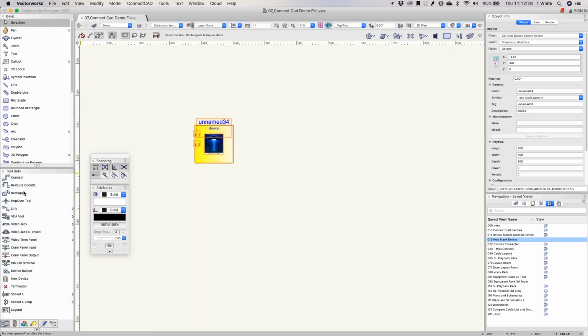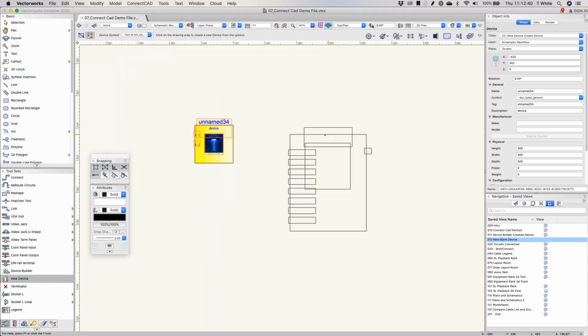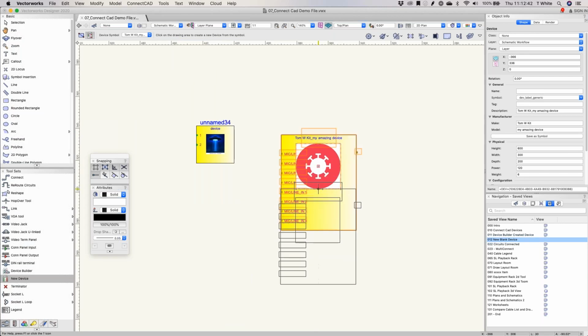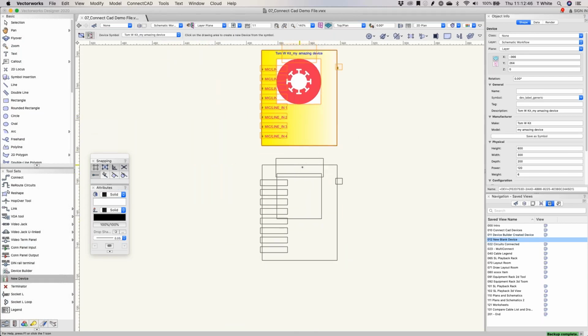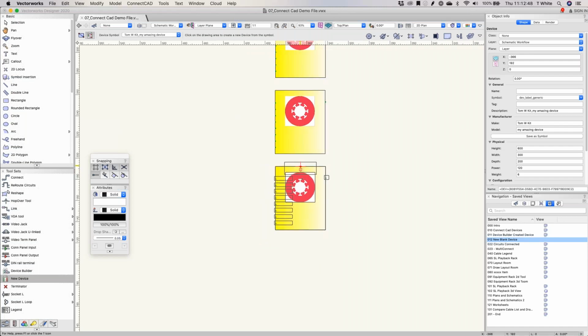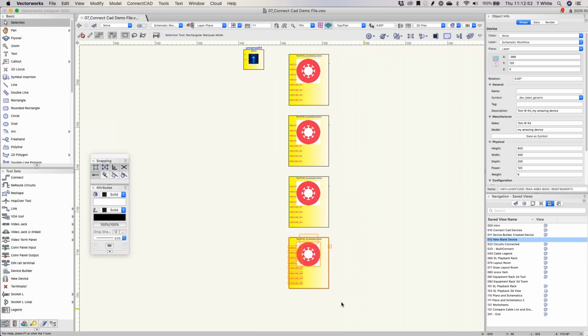This is another reason why you should really start from the template file. So when you're creating multiple devices with the Snap to Grid tool on, I'll just get my new device tool. And I'm going to pick a device in the list, as I did yesterday. So I'm going to place these. With the Snap to Grid function on, you'll notice that my cursor actually neatly snaps and arranges everything. And so it makes creating schematics really, really quick and easy.